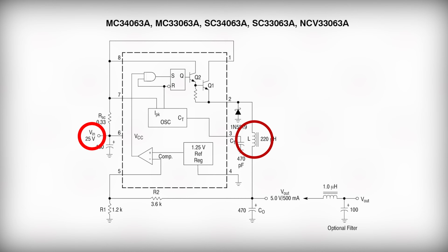I'm sure 9 out of 10 people will answer: it's obvious. We have a switching converter in front of us. Therefore, the inductor is installed here to smooth out the output ripples. However, this theory instantly fails if you ask the question, how exactly is the voltage stepped down then? We have 25 volts at the input, but there is no transformer in the circuit. So, the inductor here is responsible for accumulating energy and not for smoothing out the ripple.